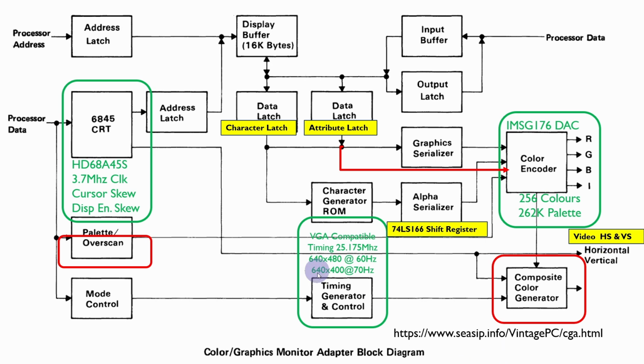Then what we have to do in our clock generation circuit is actually generate all the necessary signals to control the latches here, control the shift register here, determine when the data's ready in the RAM here and when we can load it in here. And we have to do this quite quickly in a coordinated way so that the character ROM can be finding the right character before we serialize it. So these things have to go in a sequence.